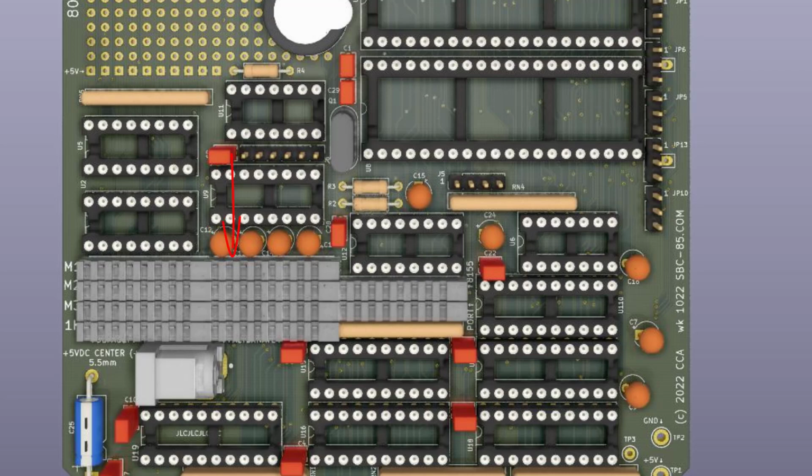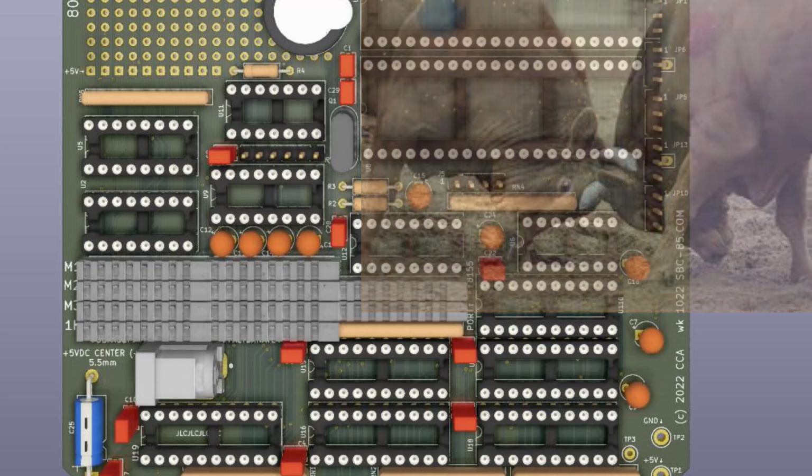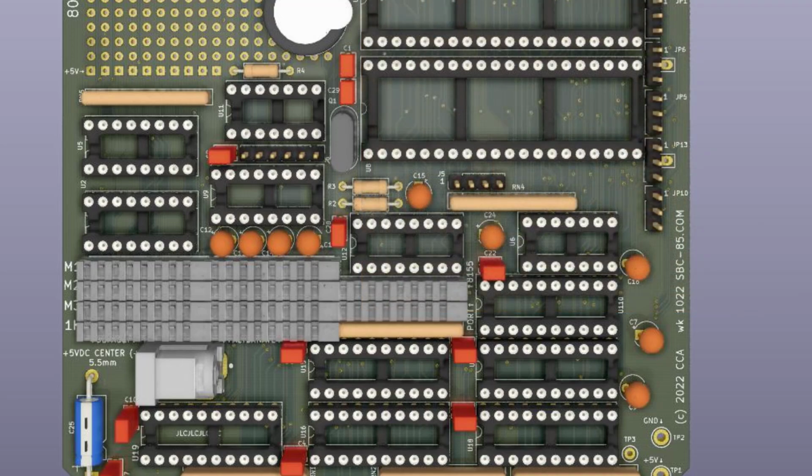Then likewise for the alternate map, you do the same. Go across these rows, make sure that any address block is only used once. And the reason that's a problem, of course, is that if multiple devices are assigned the same memory block and both are enabled, on any line where the data bits are different, they will be in contention, and so something's going to start getting hot. So we want to avoid contention on these memory devices. But I think that the way that those are arranged, it's going to be pretty easy to make sure that you don't have a misconfiguration in the memory.